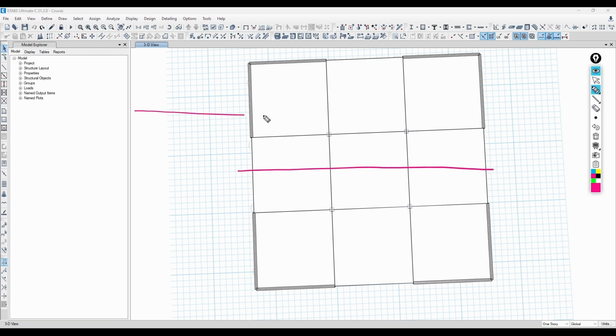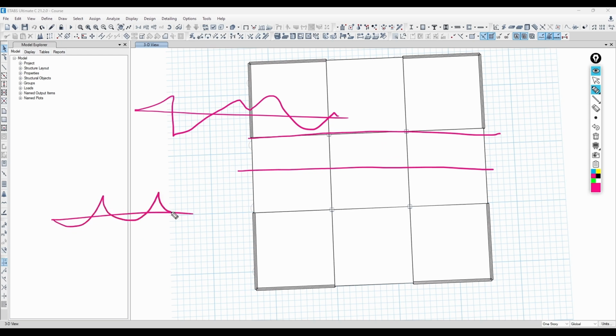So I'm going to see something like a line with the bending moments just varying on top of each other. It's especially useful if it's a field strip or a column strip. If I take a column strip around here, I'm expecting the bending stresses to be something like this, and something like this, and then go down like this, right? So this is technically a section cut. You're just cutting here, and you're looking at the slab like this, and you're getting your section cuts.